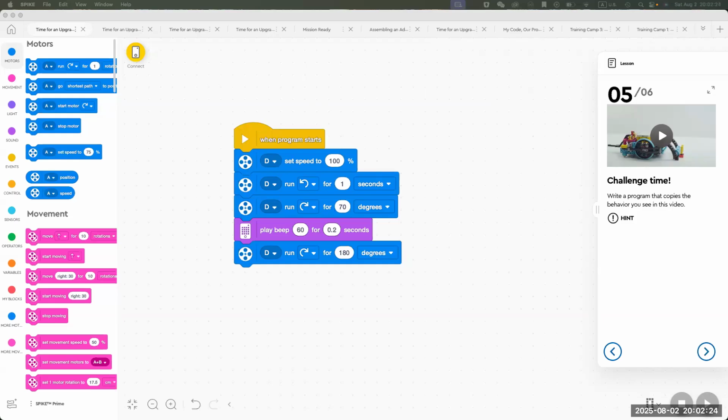All right. Third question, I think we already gave the answer in the last part. That is why we need to reset position, right? The answer is you always want to start from some default position so you can be consistent, you know where you're going. And the program, the steps to solve the problem, is more repeatable, right? If you don't start with the same position, you are likely to go too far or not far enough, right? And you are likely to miss the target, which is not what we want. Good.